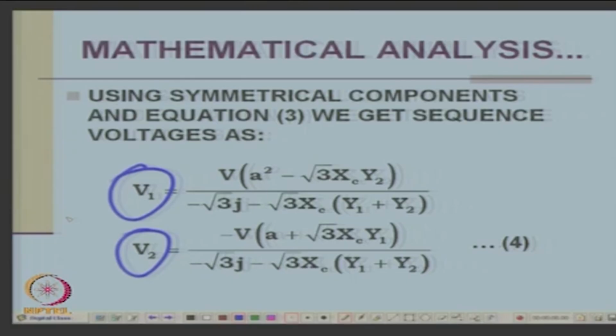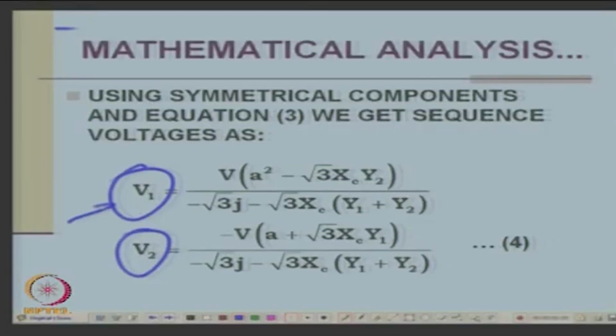A 3 phase machine operating on single phase is equivalent to 2 machines, one with V1 and another with V2, okay, and the net effect is the sum of these two. Okay. So, it is as if you are applying one positive sequence voltage V1 and then negative sequence voltage V2. Is it clear to you fundamentally? So, a 3 phase motor with single phase supply is equivalent to the cumulative effect of the same motor applied with V1 one time and V2, and take a superposition of these two. Okay. You are giving a positive sequence voltage, negative sequence voltage.